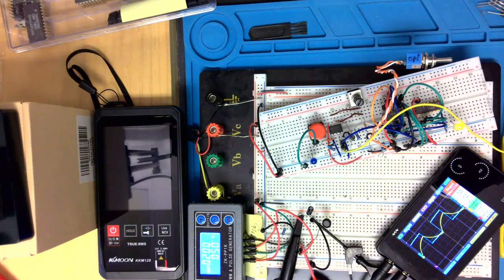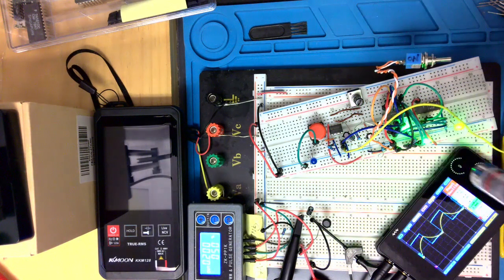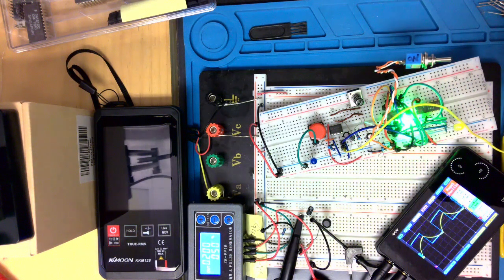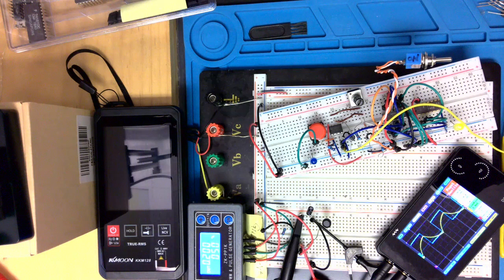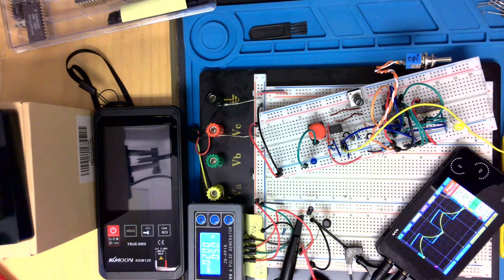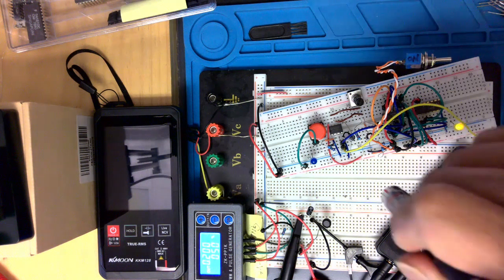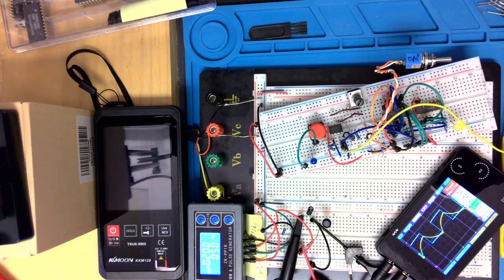What I'm doing here is this is the 555 output. I use one IC chip, a counter, to count down, because the timer is going too fast, and if you turn LEDs on and off that fast, you cannot see them. So I feed it to a counter IC chip, and the output of the chip, for example, counts 1,000 times, then the output goes to the LED.